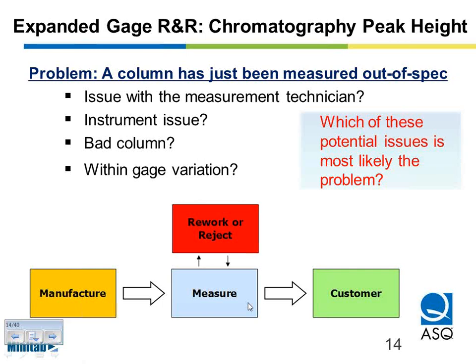So in the manufacturing process, one of the steps is to measure every single column with a standard mixture, and then see if the column is performing as we know it should perform on that standard. Based on that one reading, we're either going to scrap that column and lose all the potential profit from selling it, or we're going to rework that column if we think we can bring it back to good performance. So that measurement ended up being critical.